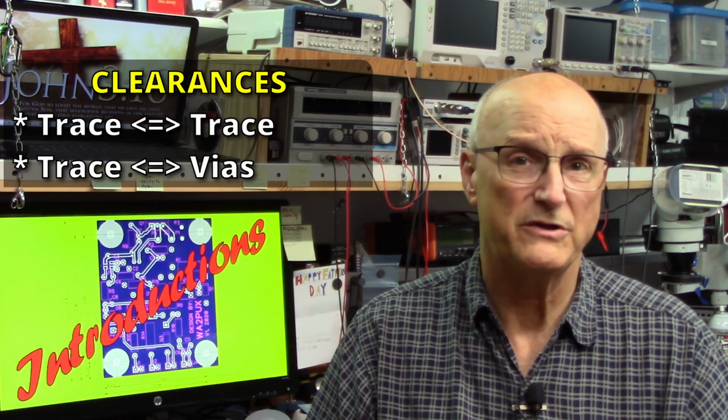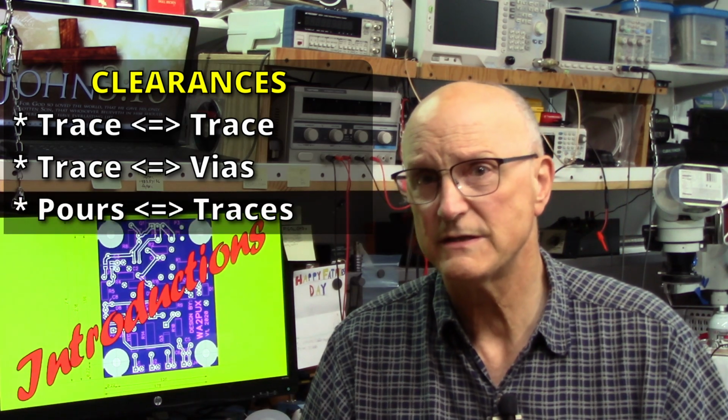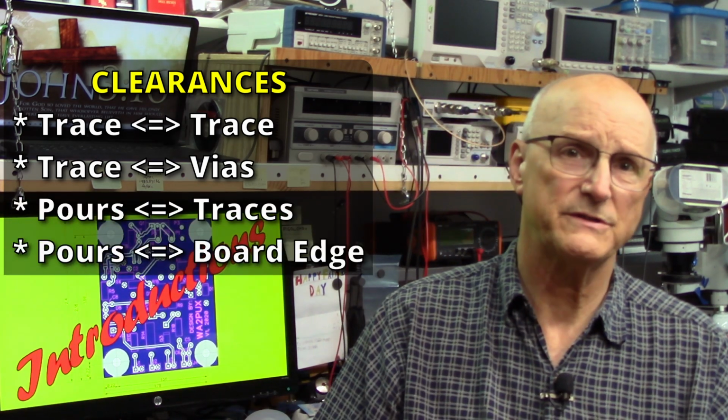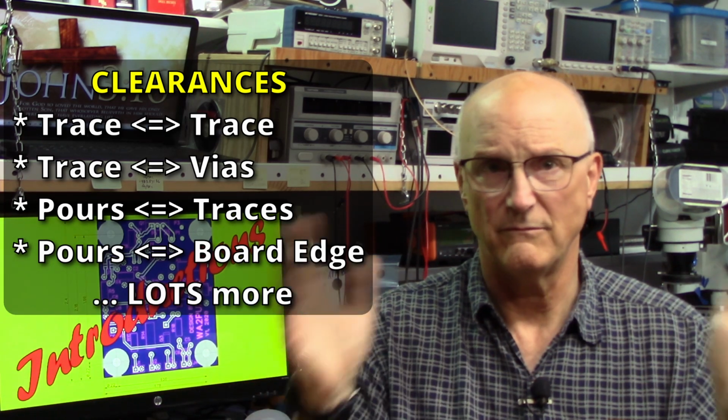And yes, you can have things very, very close to one another, but at a cost. Clearances on a PC board define the distances that are allowed between traces and vias, between copper pours and traces, between copper pours and the edge of the board, and, well, a whole lot more.